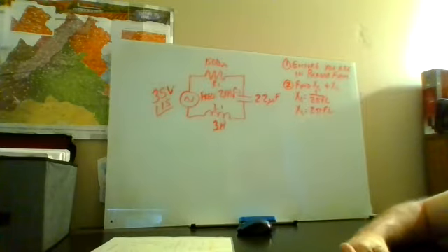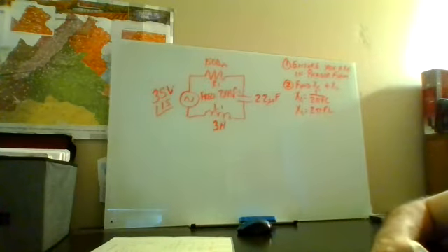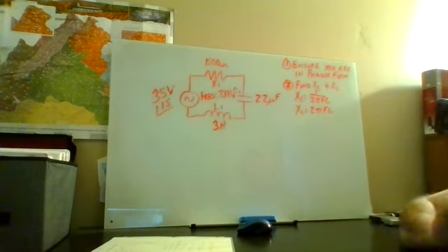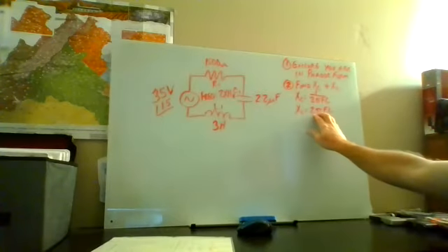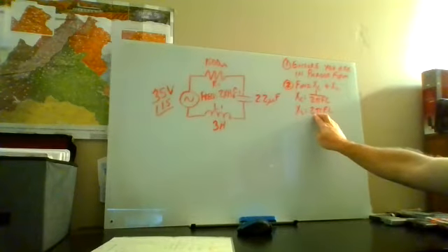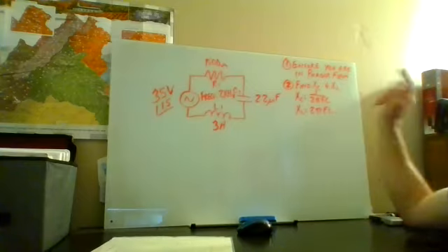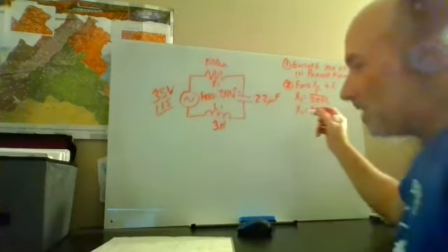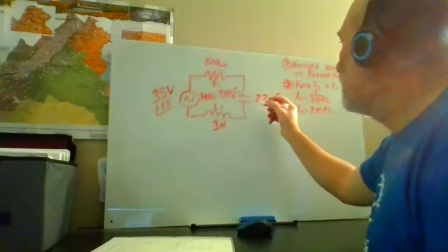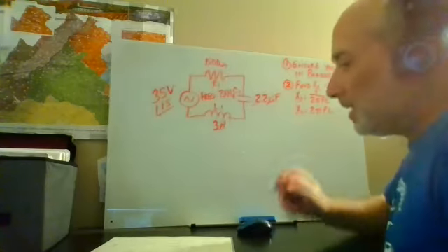I didn't do the 2 pi. I substituted the 2,000. Nope, you got to do 2 pi. The only time you substitute for the whole thing is when I give you omega. If I give you omega in phasor form, that whole number goes in for 2 pi f. Here, I didn't give you that. I gave you the frequency, so it's 2 pi times the frequency.